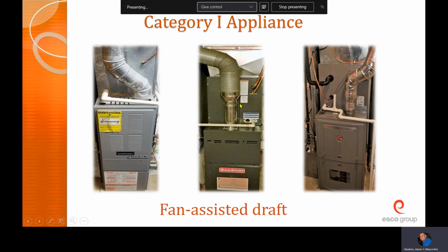You're going to want to size that to fit that furnace if at all possible. Match that up as best as you can. You can install a furnace and leave the coil, leave the outdoor unit. A lot of times people will do that. Their furnace goes bad, but their air conditioner's fine, or vice versa. Their AC goes out, but their furnace is fine. So you can mismatch those, but if at all possible, I like to match things up. Plus, it means more revenue for you, and that way you know that everything is made for each other.